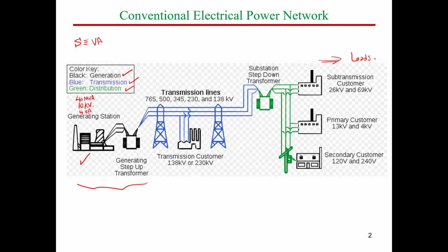Assume that the volt is here 10K and you make the volt 100K on the secondary side of the transformer. So you multiply the volt times 10. So the turns ratio, or the factor that we use to step up the volt, is 10. In this case, if we assume that the transformer is lossless, we would also have a reduction, or stepping down, of the current by 10. So we have 4 kiloampere. On the secondary side, we would have 4 divided by 10, which means 0.4 kiloampere, or 400 ampere.